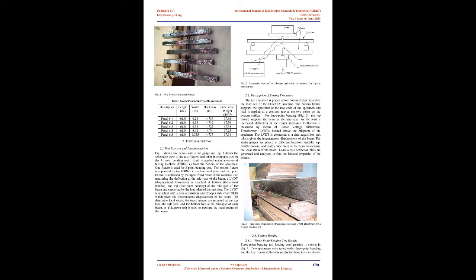Here, energy-absorbing mechanisms such as buckling and interfacial delamination in the FML skin, as well as indentation, crushing and densification in the aluminum foam have been observed to contribute to the excellent energy-absorbing characteristics offered by these systems under low-velocity impact loading conditions.